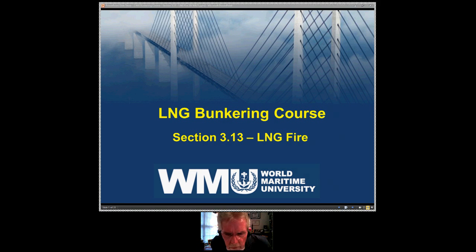All right. If everybody's ready, we're getting into a little bit more exciting area at the moment, and something that I'm sure has been in the back of everybody's mind. We're talking about keeping LNG vapors, gaseous natural gas vapors, out of air. We want to always make sure that we're out of that 5 to 15% area if, in fact, the natural gas does get into air. Exactly what happens, and what we're going to jump into here for the next half hour, is LNG fire.